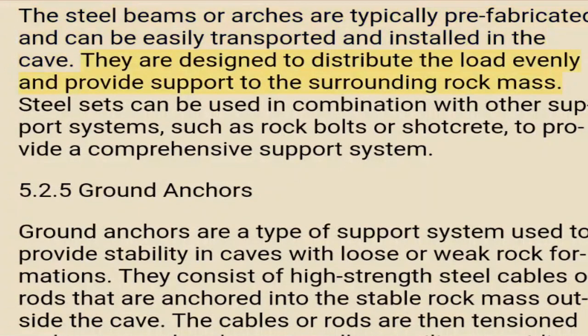They are designed to distribute the load evenly and provide support to the surrounding rock mass. Steel sets can be used in combination with other support systems, such as rock bolts or shotcrete, to provide a comprehensive support system.